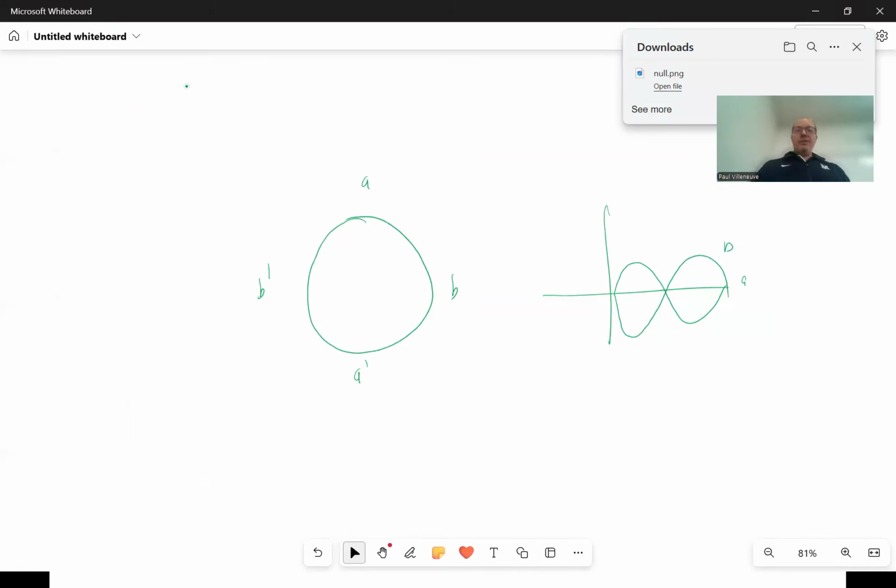So at time t equals 0, both currents are there. Going into A is 0 current, and going into B is 0 current, right? So the net magnetic field, B sub A equals 0 and B sub B equals 0. The net is the sum of those two, which equals 0. That's why we don't want a two-phase machine, right? Two-phase winding is not a good thing.